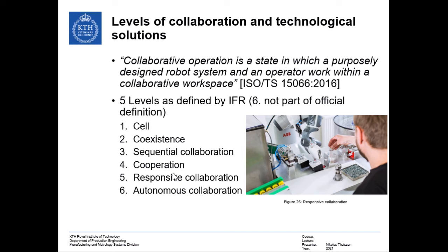Stop category in this sense means, for example, stop category 2, which is a program stop, which means that after the contact, the task program can be restarted, while there also exists category 1 or category 0, which are soft stop or correspondingly emergency stop, in which case one would need to reactivate the motors and restart the task program from the program pointer, or that is from the beginning of the program.